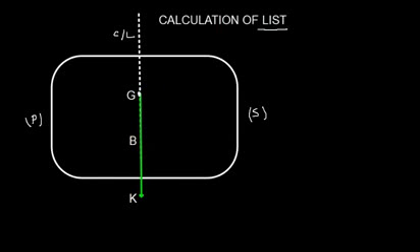And if the vessel is floating at some draft, say for example, let me just mark here, if the vessel is floating like this at some draft, the geometrical center of this underwater volume is going to be the center of buoyancy, say somewhere here, and a force of buoyancy will act vertically upward through that. The vessel is called upright.